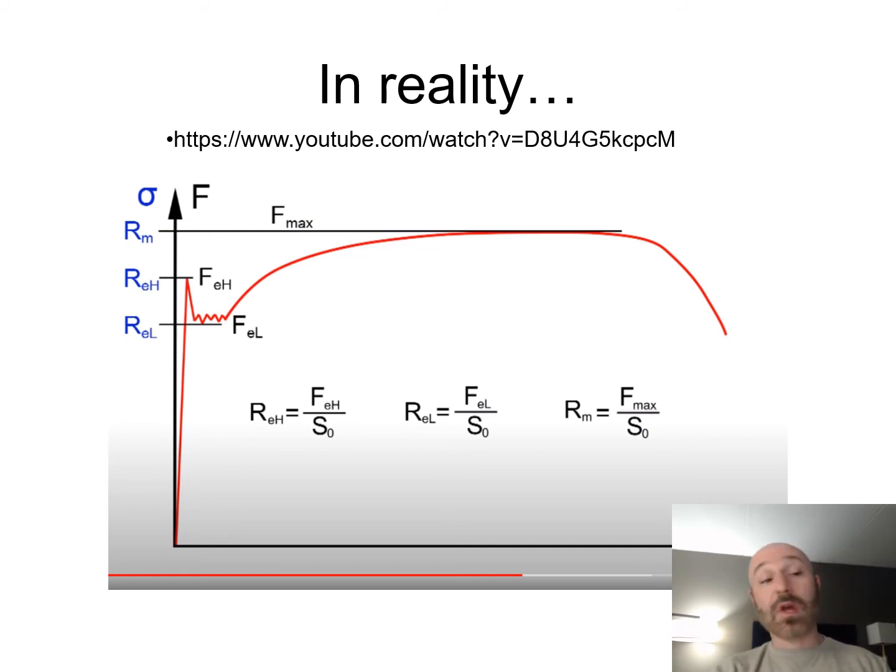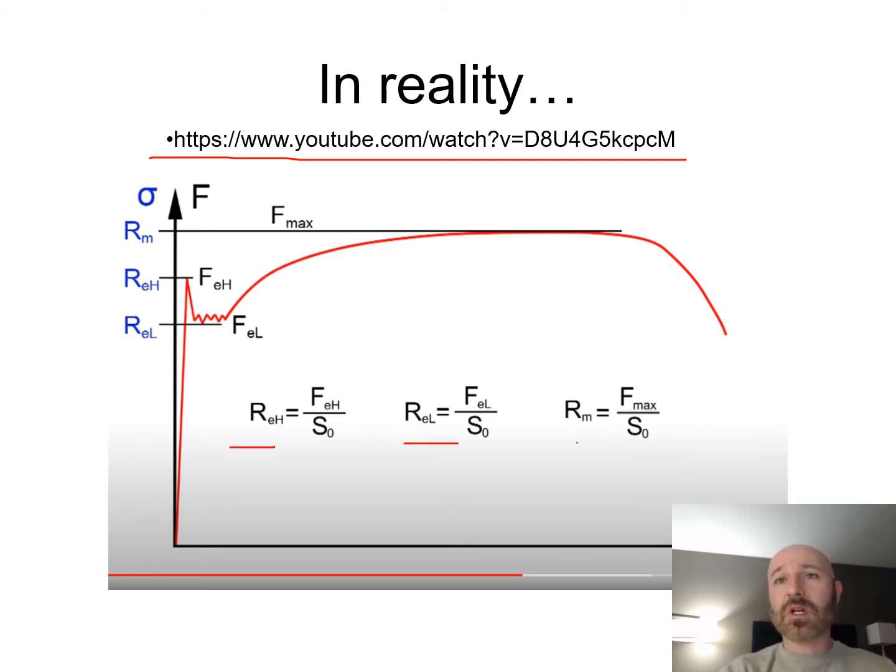That's why I think it's great to look at these different videos, and a lot of these tensile testing videos are pretty interesting and fun to watch. In general, you get some great ideas on different types of test rigs and applications, and it also gives you some background information on using this type of material. Maybe this is a good strain rate that I should use, or a good data acquisition rate. I would take a look at this and follow some of the other links that pop up for these different types of tensile testing and stress-strain curves, and look at the different variables they use and how they relate back to the typical variables in our textbook.